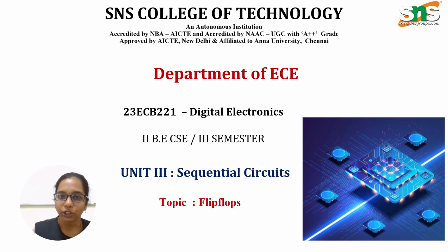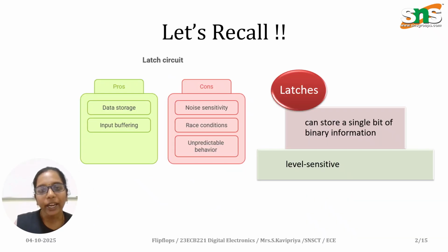I am going to discuss the topic flip-flop. Before getting into the topic flip-flop, let's recall the latches. Latches are level-sensitive devices which are capable of holding a single bit of information. The main drawback of latches is that they are not synchronized with the common clock pulses, and there is a race around condition that occurs in latches, which means that when inputs are 1 and 1, an invalid output exists. These drawbacks are overcome in flip-flops. So latches are the basic building block for flip-flops.